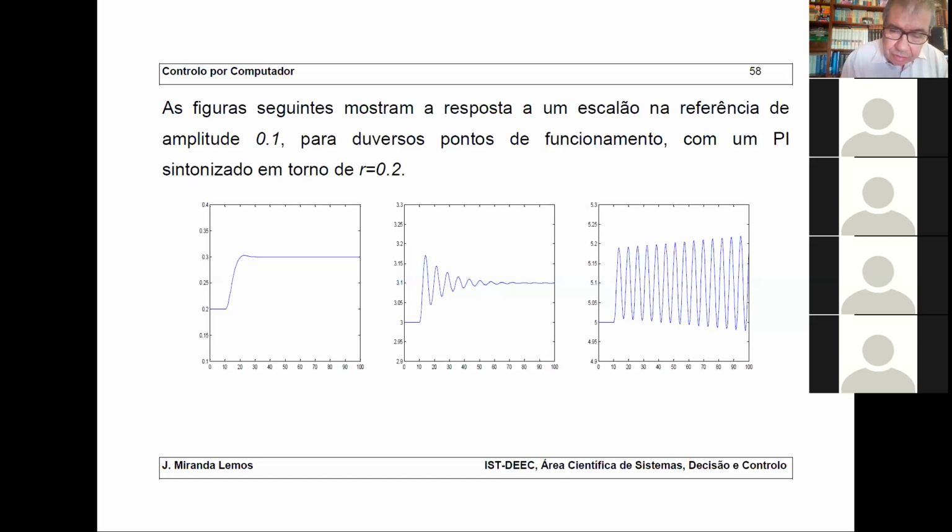And the exhaust gas passes a point where there is a sensor called the lambda sensor, and the lambda sensor measures the excess oxygen, okay? The excess oxygen in the gas going out from the combustion determines the efficiency of the system.